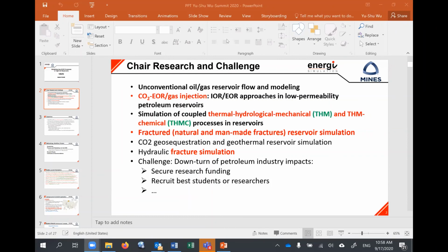Okay, I suppose this question from Osama Jivali refers back to CO2 injection. Would CO2 become supercritical, is that correct, as you inject into the deeper, hotter reservoir, right? Yeah, in most cases, we hope so. Definitely we want to reach minimal miscible pressure, right?